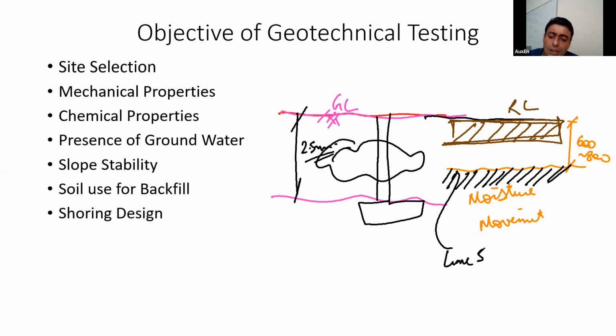So we put some lime solution, lime plus water, and we just fill this layer. We give this dosage to our top soil after 800 mm layer removal. So this soil gets stabilized to a certain extent, and then you can put your compacted sub base, whatever you want to put, and that's how you can do your road level. That is the second option.